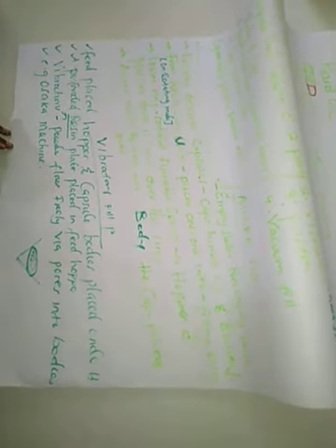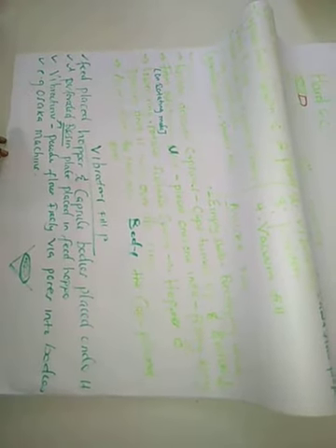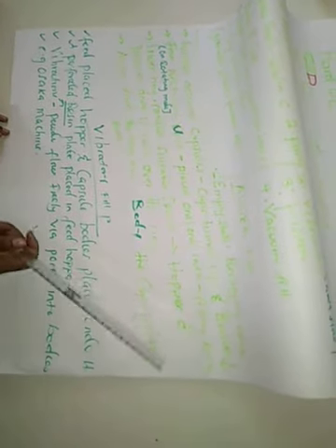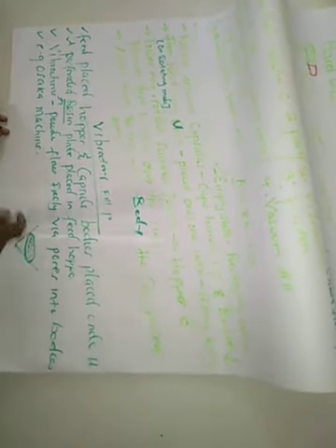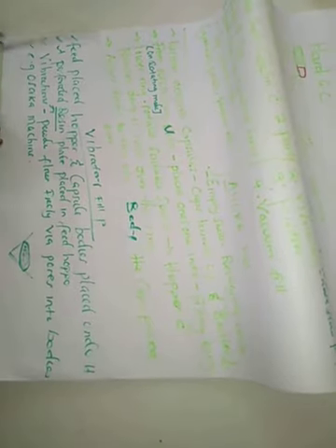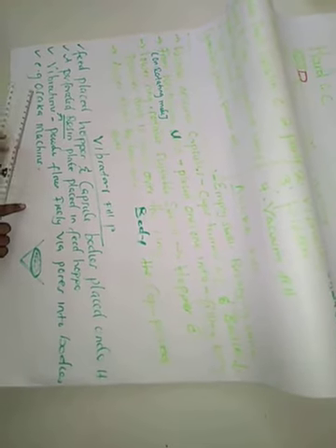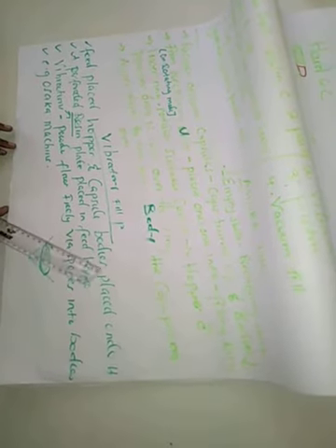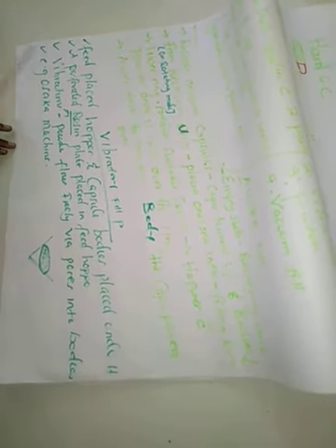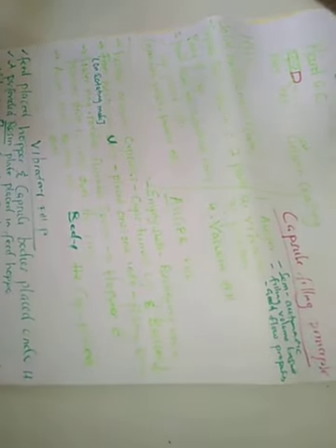This feeding ring is on a rotating mode. Why rotating? Because it facilitates feeding of the body capsules, so it has to rotate at a suitable speed. As it continues to rotate, the hopper placed over the ring, with the help of the auger, drives the drug into the body capsule. This is semi-automatic, so the caps are then placed over the bodies. Normally that's what happens. The other one is the vibratory principle, where we apply vibration.